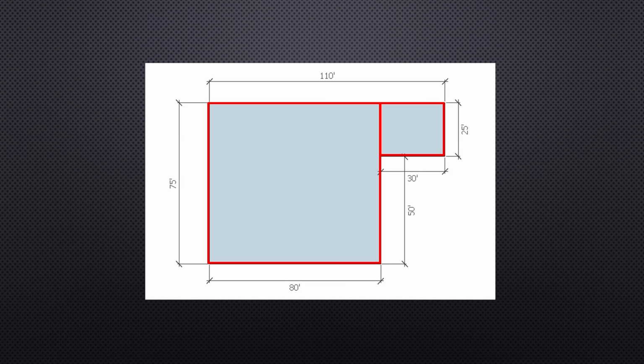Well, technically you could. Since the smaller section is more than 320 square feet, you can even use perpendicular and parallel lines since the width is 25 feet. Remember, it's less than the 25 feet that is the breakpoint that forces you to use the 45-degree method. The only gotcha is that you cannot observe the 2-foot boundary rule in this section. Let's draw in the 2-foot boundary so we can do the math and show you why.